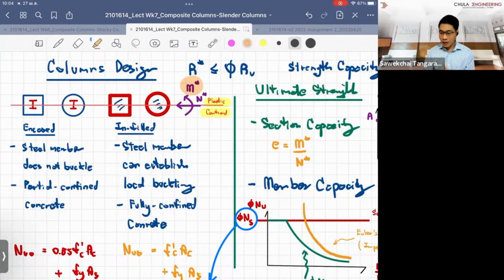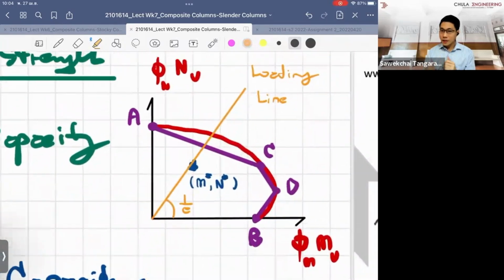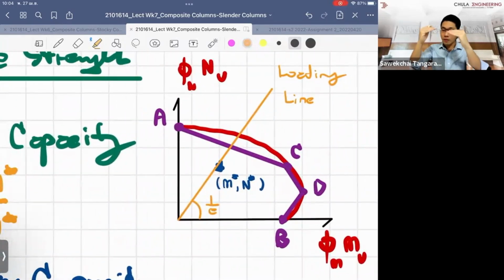We can use this concept to calculate the capacity when we rearrange the line of the plastic neutral axis. The plastic neutral axis tells us where the line is that divides the compressive stress and the tensile stress. So we just keep changing the level of the plastic neutral axis. The more you change it, the smoother the curve. But if you consider only 3 levels of the plastic neutral axis, which can be used as an approximate diagram, we call it a piecewise linear diagram.